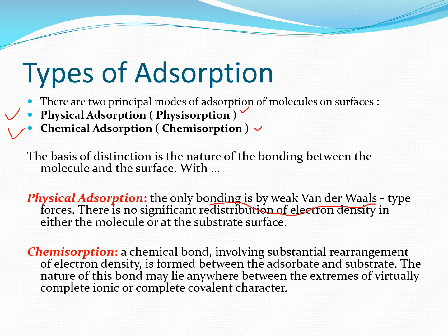So I will just explain that we have two types of adsorption. In physical adsorption, the adsorbate molecules only retain on the adsorbent, and that can also be reversed. Whereas in chemical adsorption, a chemical bond is formed between the two species, adsorbent and adsorbate, and it cannot be reversed. Mostly we will focus on physical adsorption, because chemical adsorption is basically a chemical reaction, and the whole adsorbent bed needs to be replaced in that case.